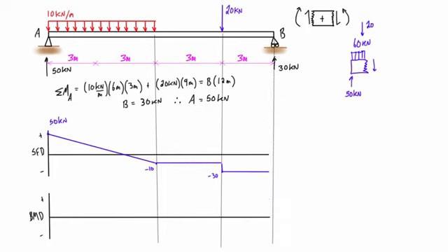Alright, close enough. One thing you want to do at this stage is make sure that where we're ending with shear makes sense. So if we consider the free body diagram from the other side, if we section just to the left of that support, we're going to have 30 kilonewtons pressing up from that reaction force, and we'll have some shear force. That's going to have to be 30 kilonewtons pressing down in this region, and when we look at the left hand side of a cut, positive is in the upward direction, so that's going to be negative, so it'll be negative 30 kilonewtons. That's exactly what we're seeing for our shear force right at the end there, negative 30 kilonewtons. Alright, so that looks like we've done that properly so far.